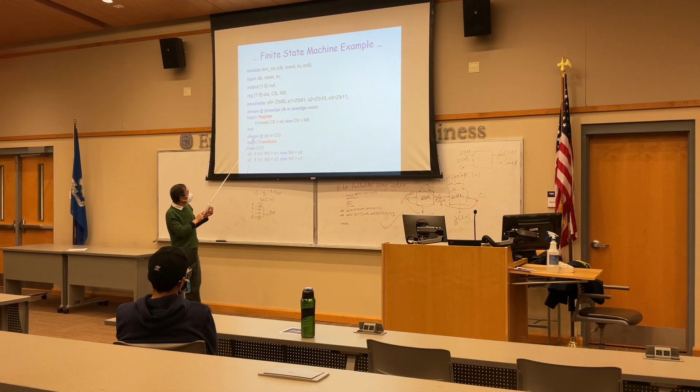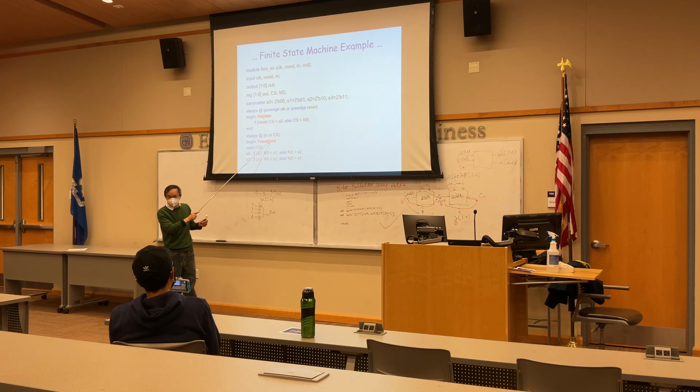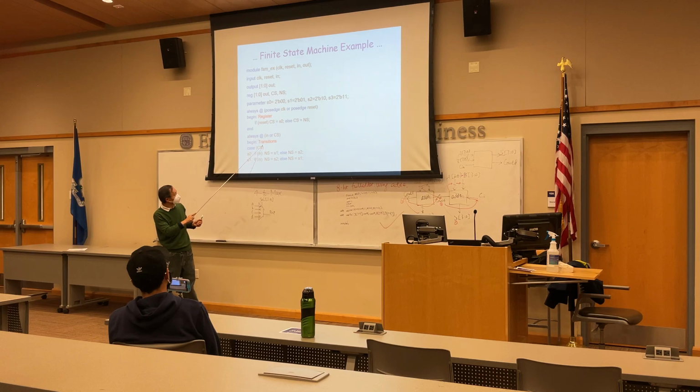Now here, we are going to use 3 always blocks. An always block for the reset and the state transition, an always block for the STG description, and an always block for output generation. Using the current state or input to trigger this always block: case current state.